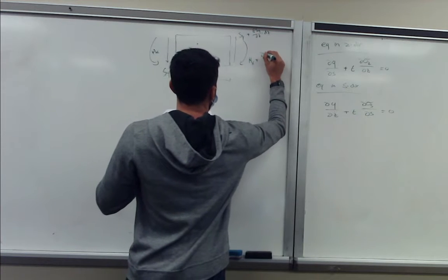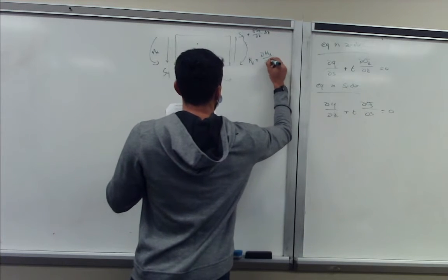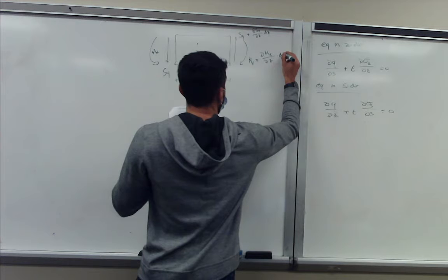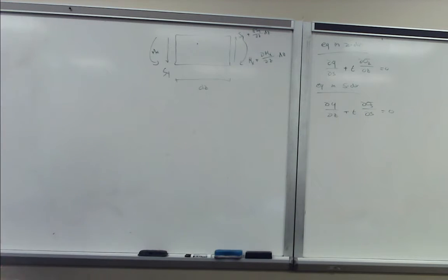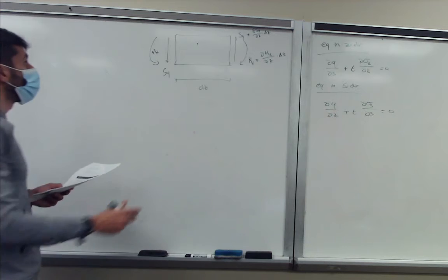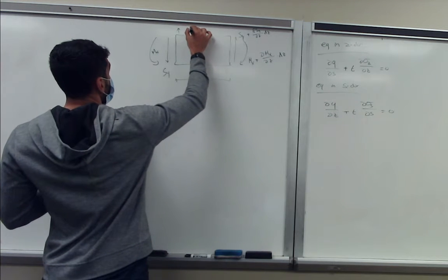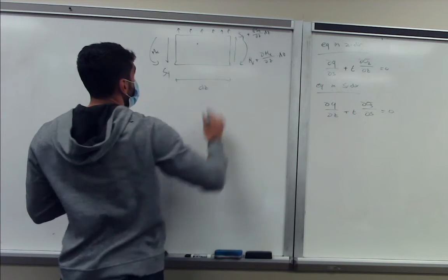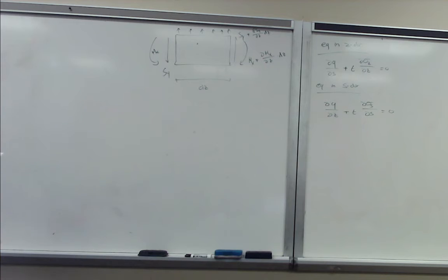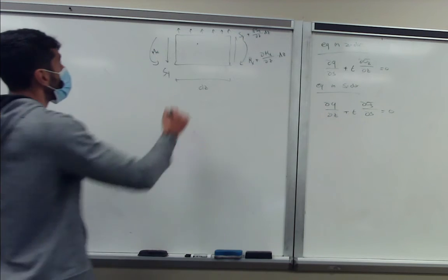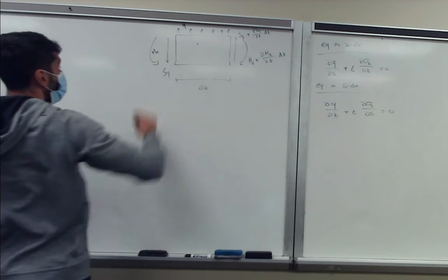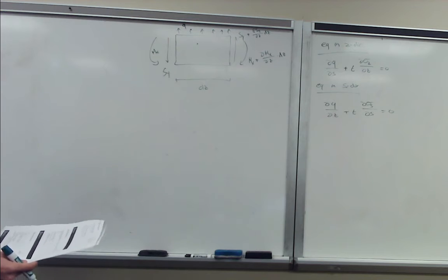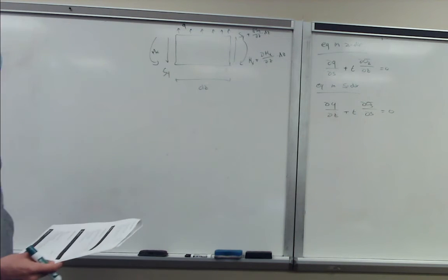And on this side, we must have Mx plus the variation of Mx in z multiplied by the differential element dz. And we're looking at a distributed load as well. So it's a unit force per unit length. This will be our Q. This will be a small incremental element in any beam, for example, or any structure. We can identify such an element.